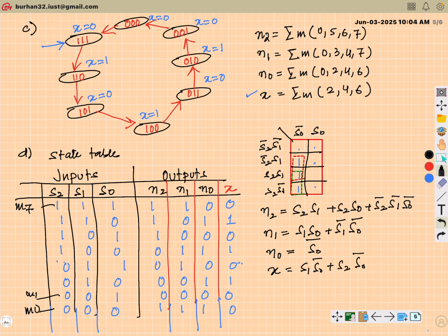So this is yet another counter, the up count, the down counter. The important thing here is that apart from this main counting process, you can actually also involve the inputs and the outputs to add additional functionality to your circuits. Like with the down counter in the last video, we included an external input B, which actually controlled the transition from one state to next state.